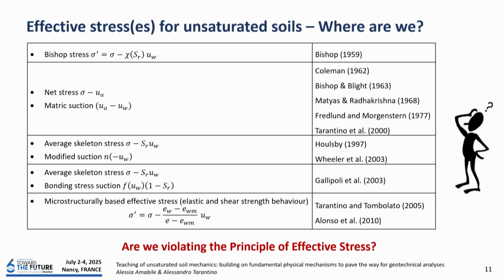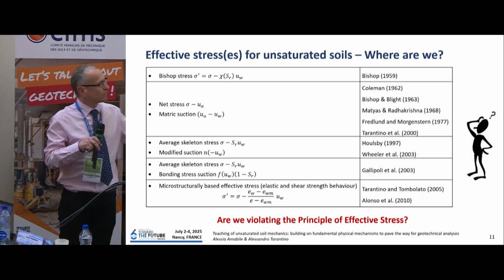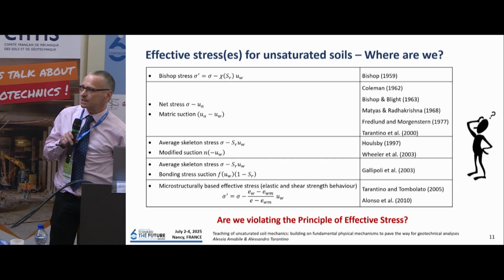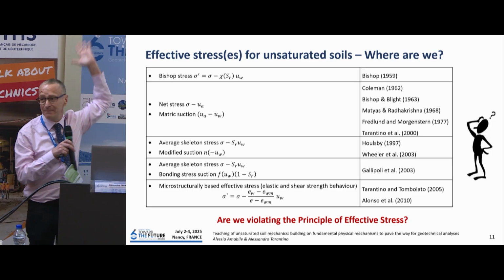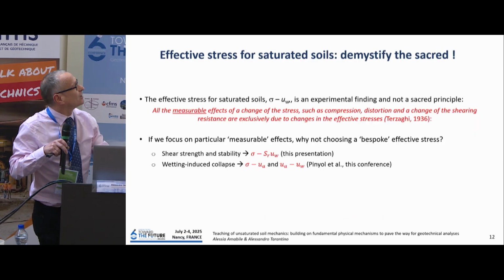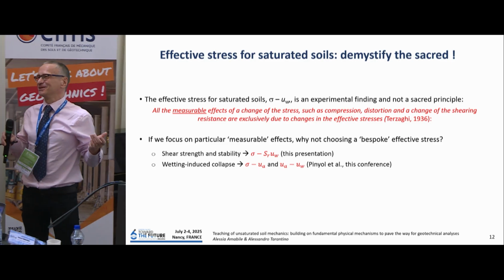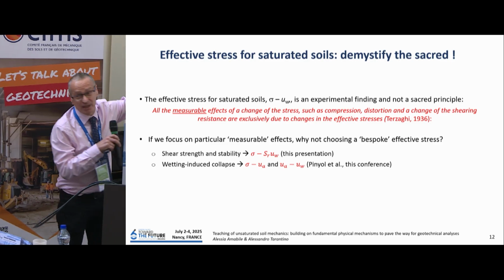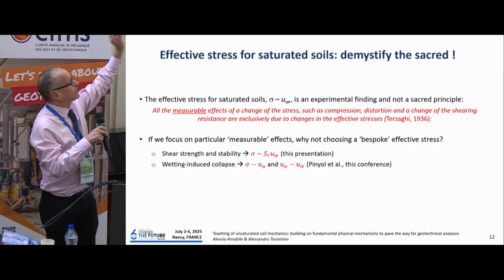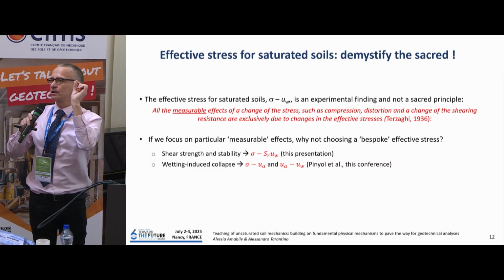That's a non-comprehensive list of effective stresses. Oh, the first reaction of a saturated teacher: we are violating the principle of effective stress. Okay, let's dismantle the principle of effective stress. That's the original definition by Terzaghi. The key word here is measurable.